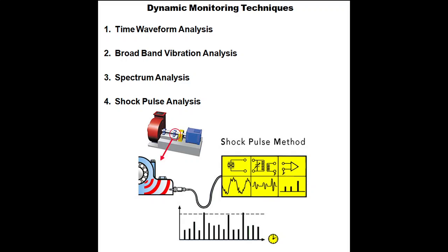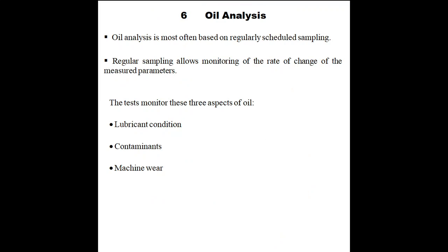You can see in the picture that we are using a bearing, and you can check the shock which it gets due to operation. If the shocks, the vibration we are getting, are within the given permissible limit, we may say that the machine is working well. But if these values go beyond the permissible limit, or change very unexpectedly, then you should always be ready to check the setting of the part. So this is how dynamic monitoring techniques work.